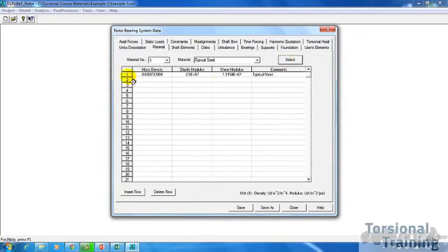So what it does is it populates this first row, and the mass density that it calculates is 7.32 e to the negative 3, I believe. And it leaves the density. Again, don't forget we're dealing with consistent English units, so we have density in terms of pound force second square over inch raised to 4 instead of the classic pound mass over inch cube. And the shear modulus 1.154 e to the 7 psi, pound force over inch squared, and the elastic modulus.